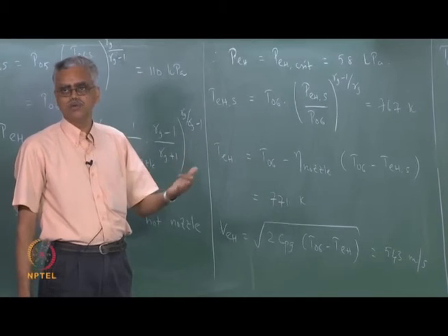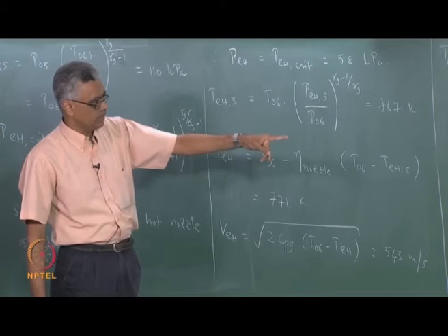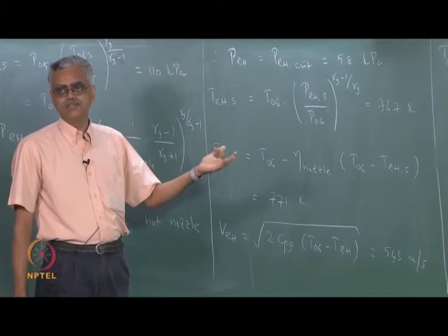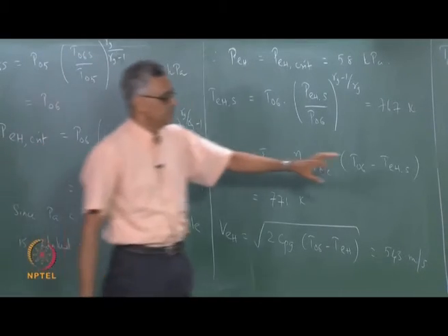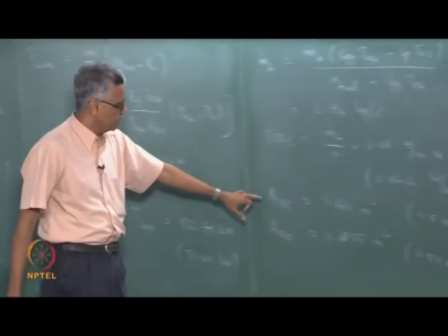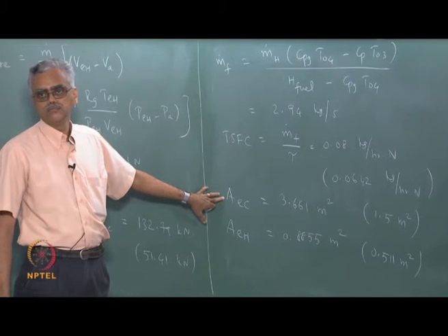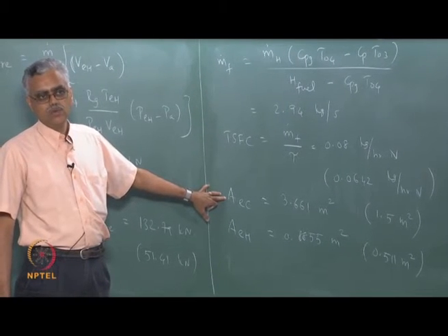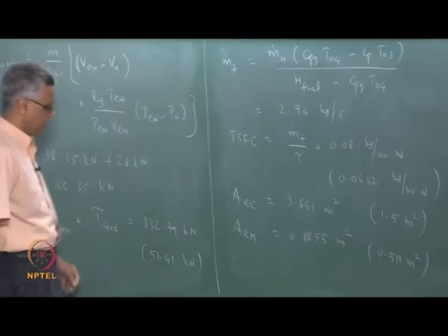Everything was taken into account properly. Everything was a ratio. So if I scale down the mass flow rate by a factor of half, VEC will remain the same, and I should be able to get a better agreement with manufacturer quoted values. So that I can do for one nozzle. Then what do I do with the other nozzle? That is the question that we must answer next. Let us see what happens with this.